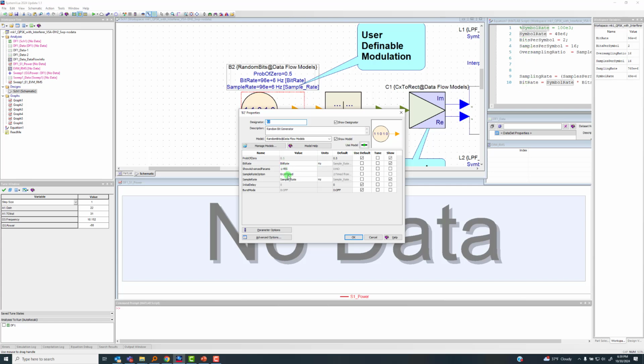And so it's set up untimed, because we're going to add timing information later on in this data flow simulation. But off the top, it's just generating the bits, as we've governed here, pseudo-random bits. By the way, the sample rate variable in the bitrate source is set to sample_rate. That is tied to the data flow controller. That is a reserved variable, sample_rate.